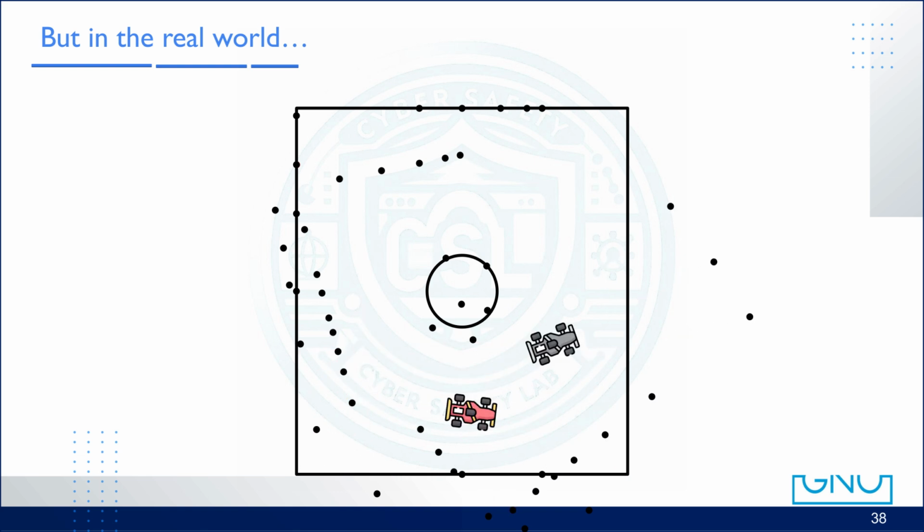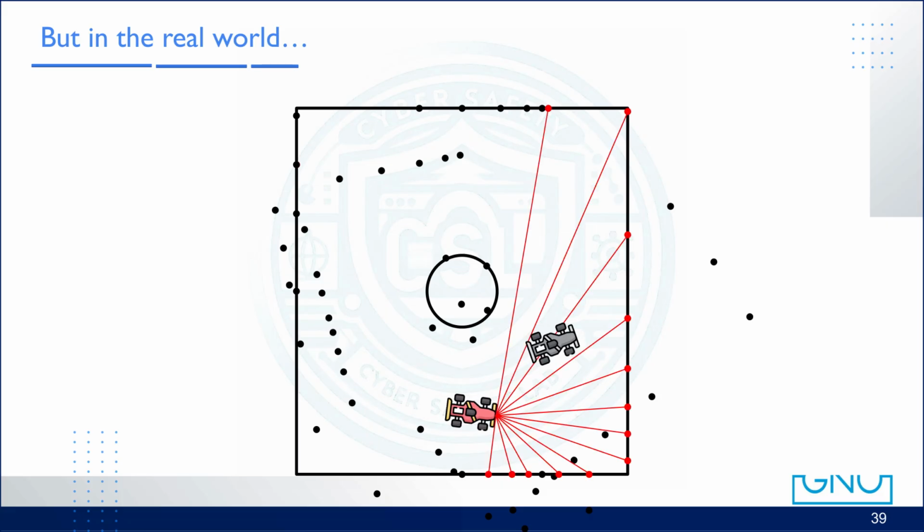As the robot keeps moving, the error accumulates further. Each LiDAR measurement is still mostly fine, but because the robot's estimated pose is wrong, all points are projected incorrectly. Walls that are straight in the real world begin to appear stretched or curved in the map. The distortion grows over time.